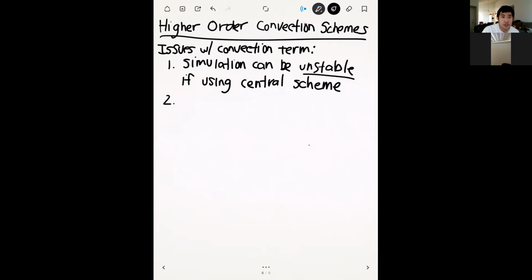In finite difference, we saw that by using the backward difference scheme for our derivative, and for finite volumes, we saw that we can do this by using the upwind cell instead of the average between the central cell and the neighbor cell. So we already know how to deal with this within reasonable bounds.